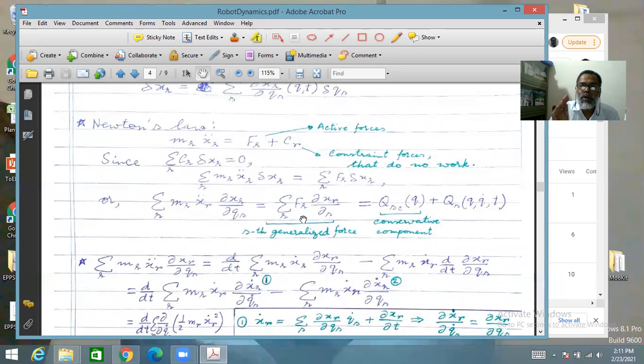Okay. Now, depending upon whatever that generalized coordinate is, position, angle, or something else, the quantity here will turn out to be force, moment, or appropriate something else. So that the generalized force into generalized coordinate, the product matches the dimension of work and energy. So in that sense, it is generalized force. Now here the derivative is with respect to delta qs.